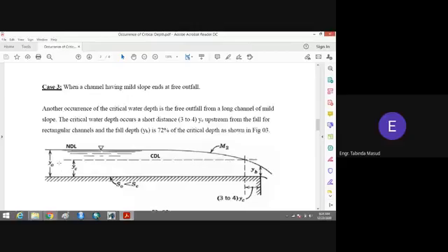It will obviously be a subcritical flow, and exactly at the outfall, the depth of the flow is known as the brink depth, and it has been observed that the critical depth will exist at a distance of this term, yb is equal to 3 to 4 times yc.